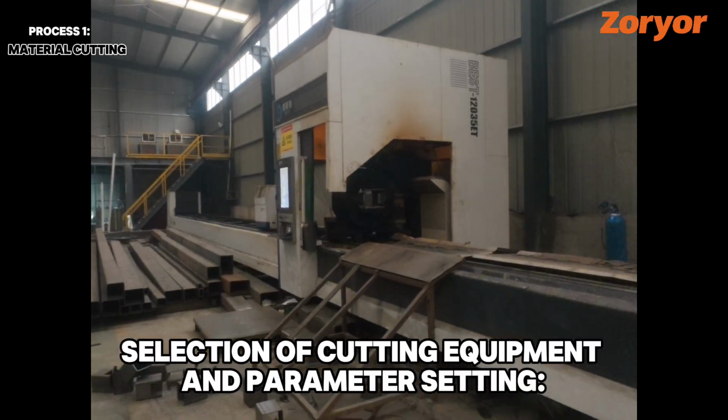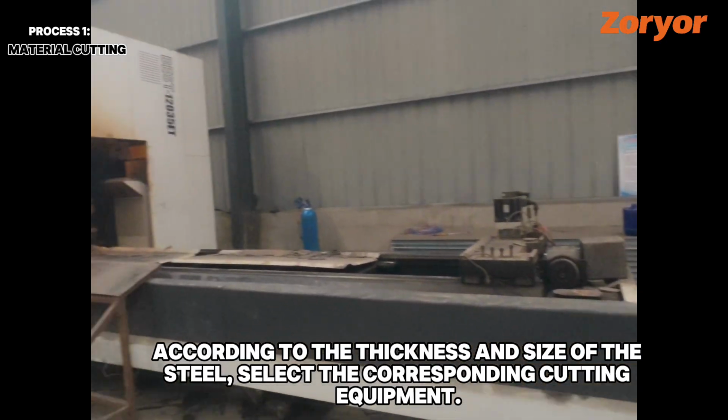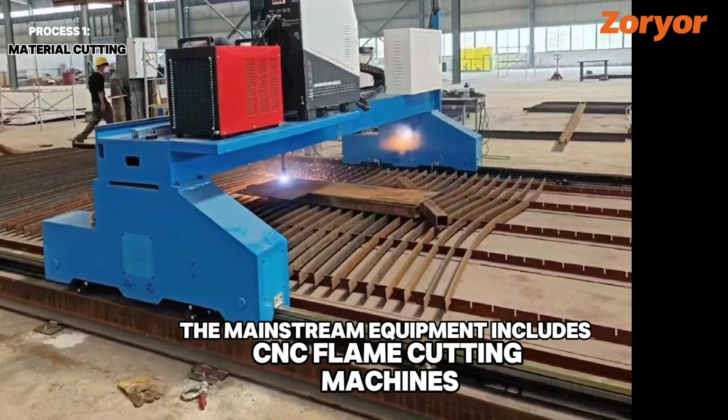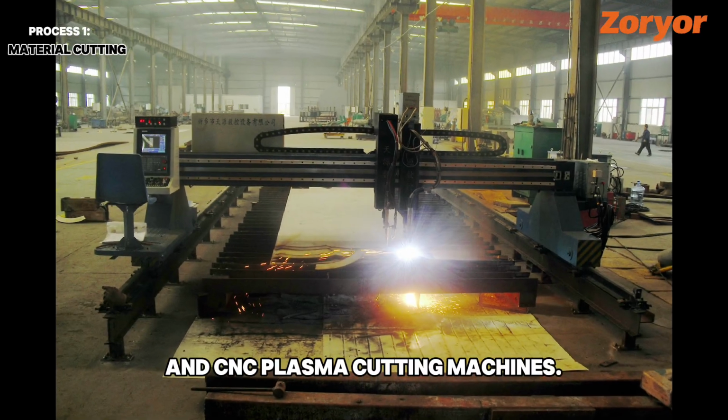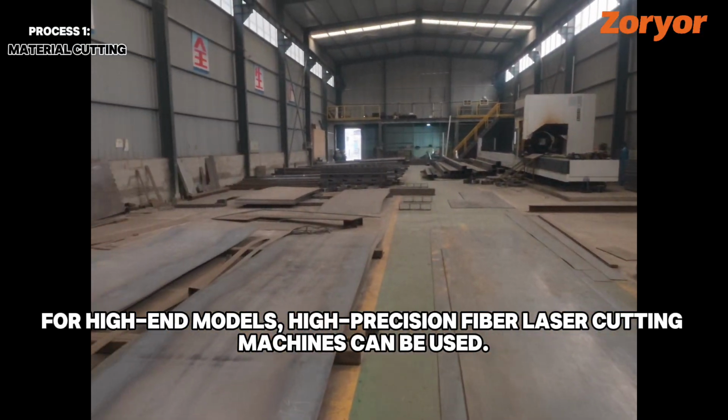Selection of cutting equipment and parameter setting. According to the thickness and size of the steel, select the corresponding cutting equipment. The mainstream equipment includes CNC flame cutting machines and CNC plasma cutting machines. For high-end models, high-precision fiber laser cutting machines can be used.